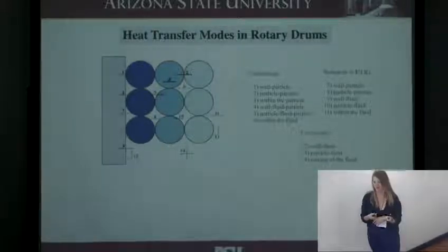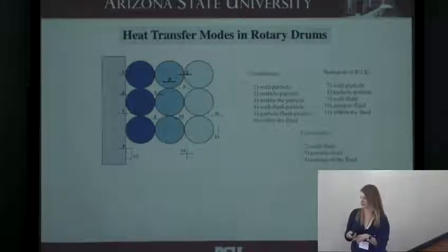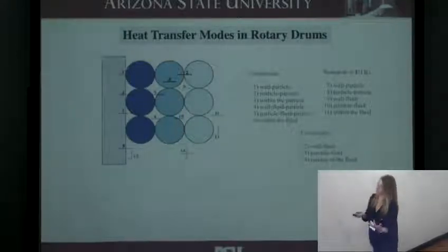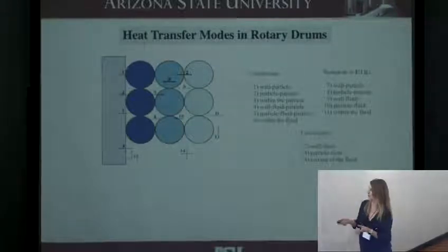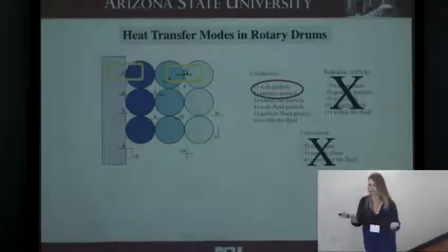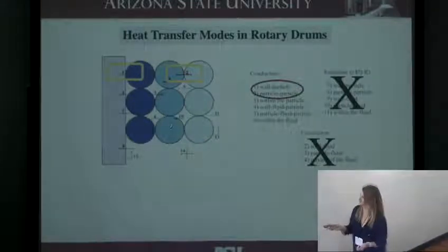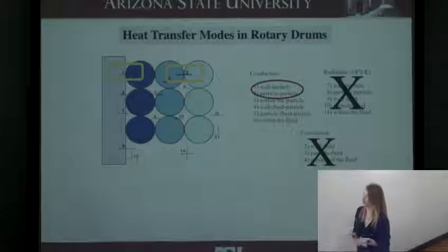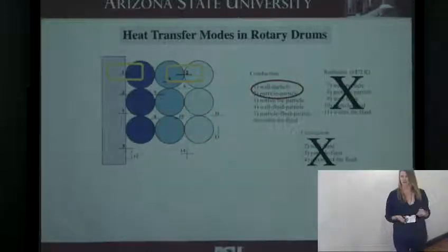Radiation becomes really important above, like Ray said, about 600 degrees C. So below that, for dense phase systems, it's pretty much conduction dominated. So to start, we're focusing on conduction, so the particle-wall and particle-particle conduction, but we eventually do want to get to these other stages.